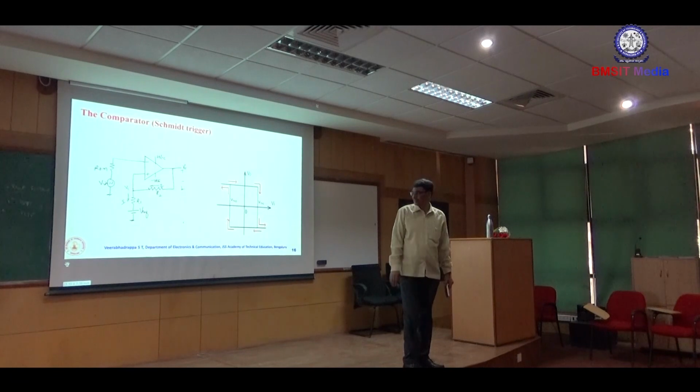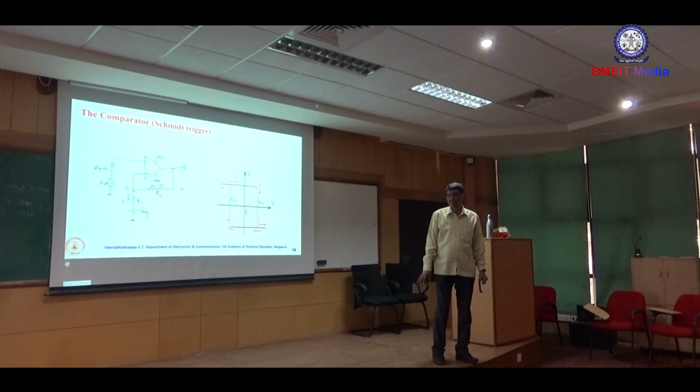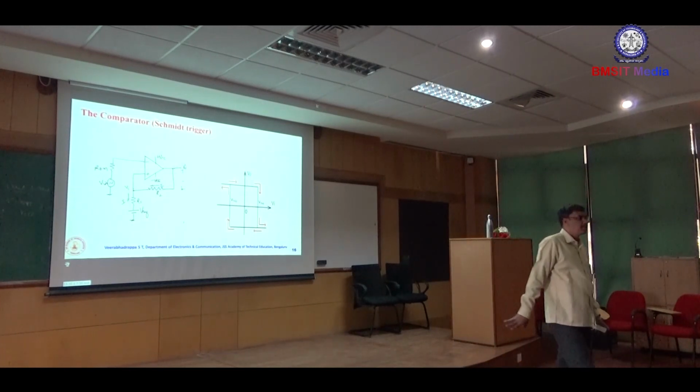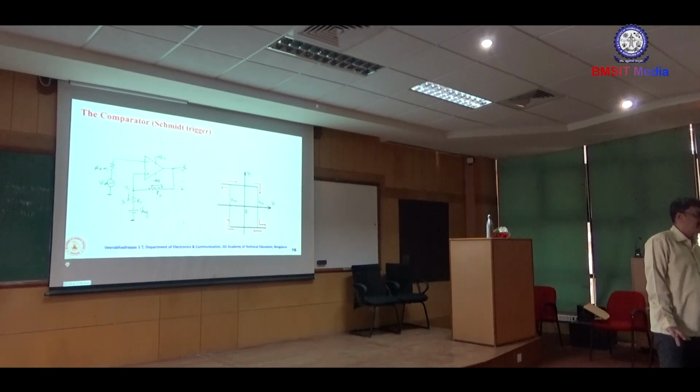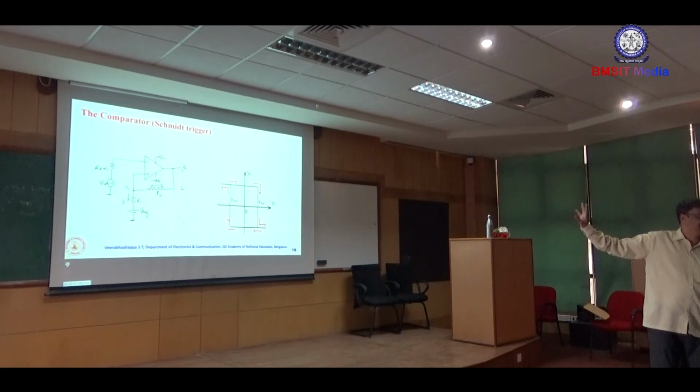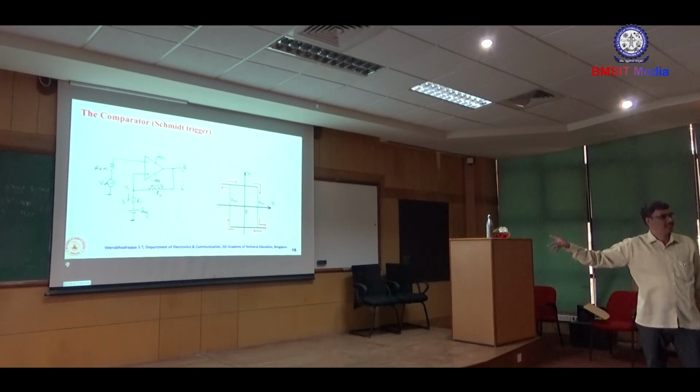But when the reference voltage is zero, there is no difference from a zero crossing detector. Instead it depends on the values of R1 and R2, and you get identical symmetrical square waves. But the threshold values are non-zero, whereas in a zero crossing detector they are exactly zero.